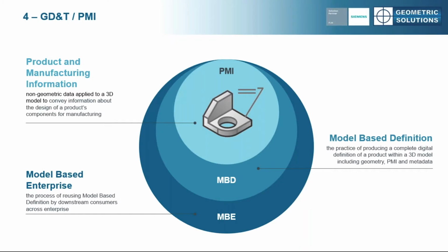So I started talking about PMI. There are other terms related to that, and I just want to talk about those. PMI is the heart, right? It's basically non-geometric data applied to a 3D model. But there's a term called model-based definition, which is typically the practice of the complete digital definition of a product within the 3D model.